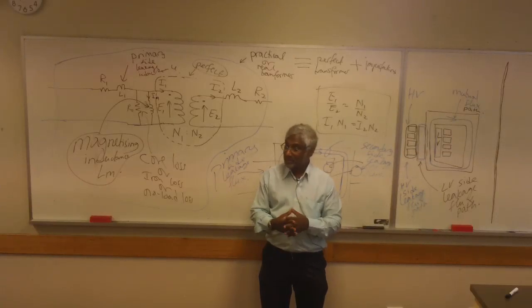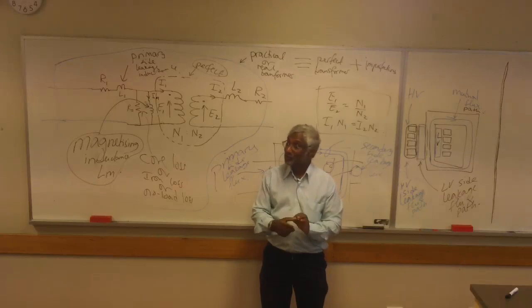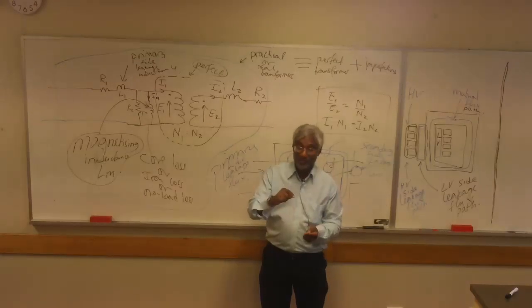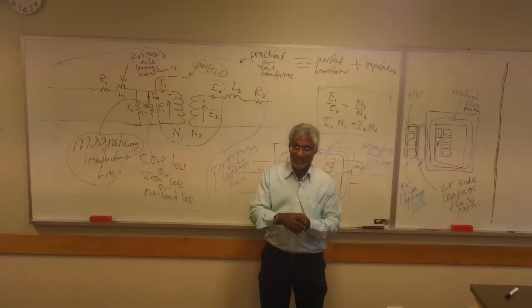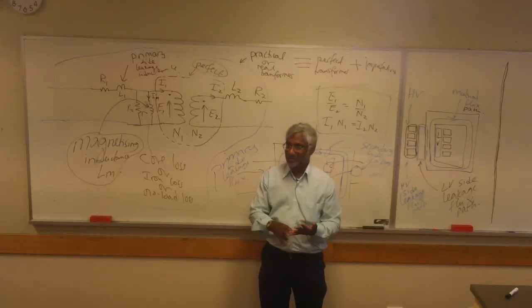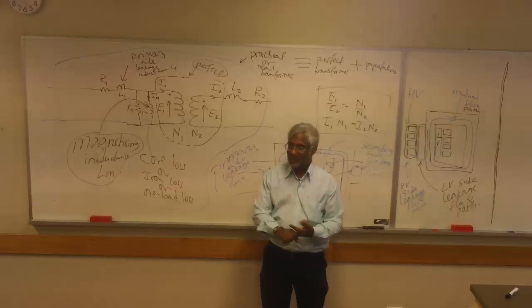And there is another one that's mentioned from time to time, and that is turn-to-turn capacitance. From one turn to another turn, you have inductance, but you also have insulation, so that creates capacitance. So turn-to-turn capacitance, winding to winding capacitance, and winding to earth capacitance.